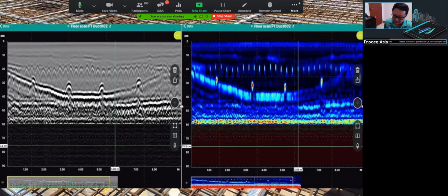This result we collected in Singapore at the I3 Research Center, when we were doing the exhibition over there. From this result, we can see the first layer at around 15 cm. This is because there's a plaster layer, which of course increases the cover of the rebar.